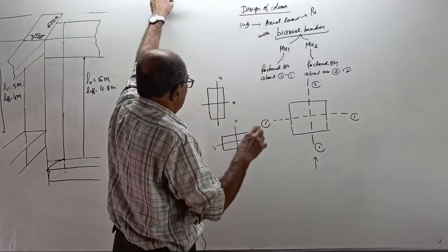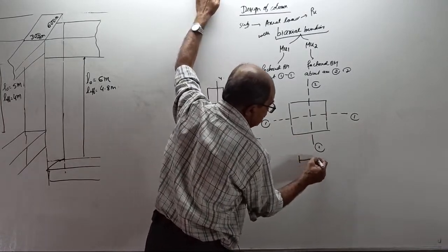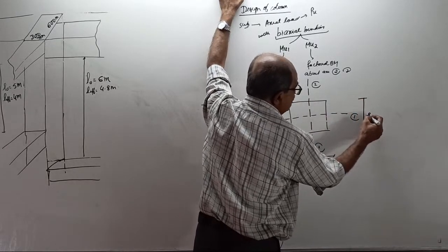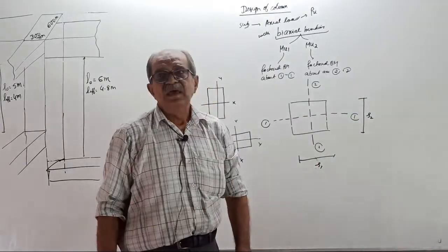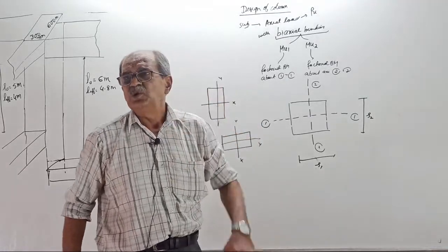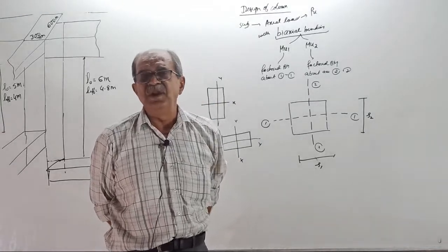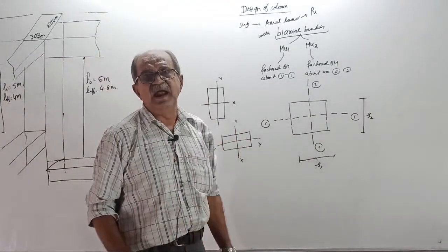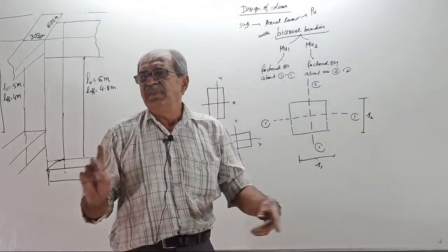See, now suppose I take a section here. This side I will take S1, permanent in my class. In our class, no confusion, S2. When you go to the Excel sheet also, do the same way. And one more thing, remember, the Excel sheet is required only for those who are going to do manual design of the column. Actually, for column design, you don't have to do anything. Prepare the model in E-tabs. That is our course. Apply the load, create load combination, analyze and design.